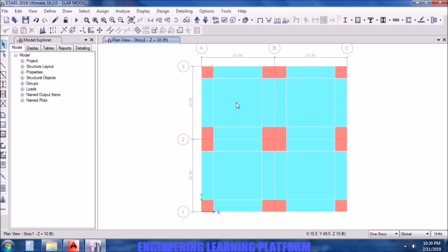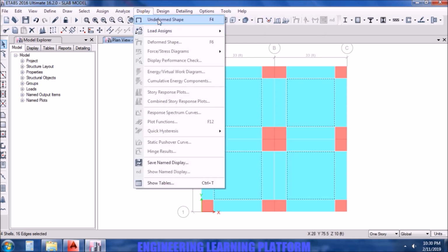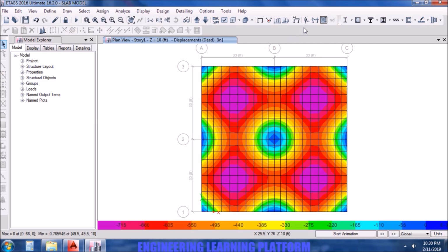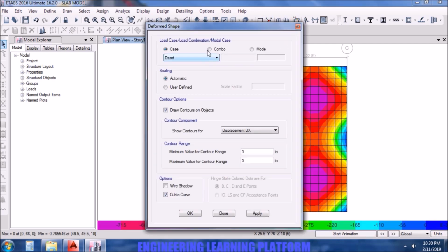Unlock the model. Since the deflection is exceeding the limit here, we will provide camber in these selected regions. So let's ignore the deflection exceeding the limit here, as we are able to provide a camber of approximately 2 inches, which we will later calculate accurately in this video.